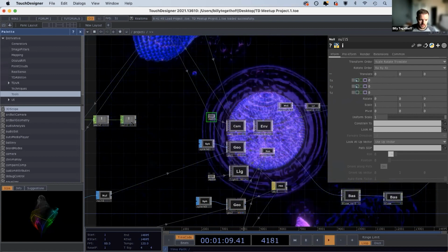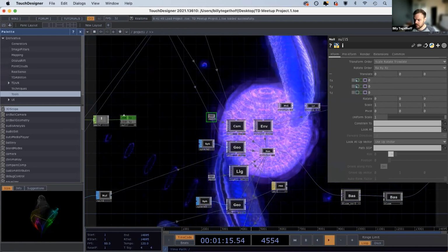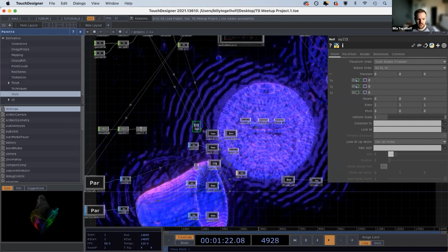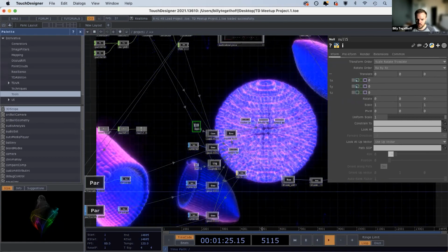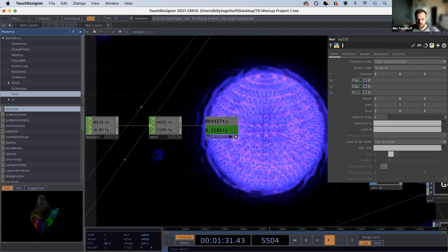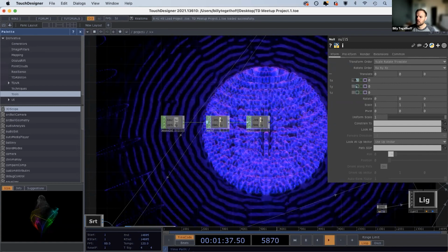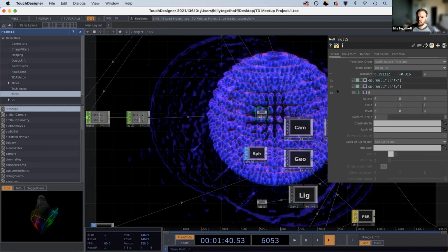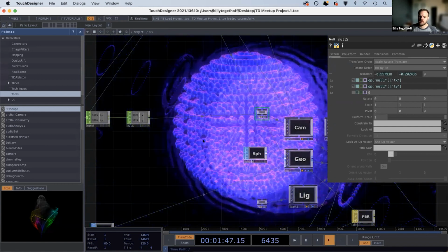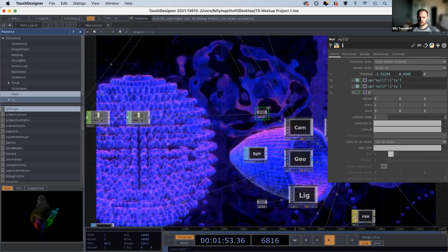Now, what you can do with that information, and where this gets interesting, is you can animate your look at point. If you don't want it to always look at the origin, the simplest version of animating it that can get a cool handheld camera look is using the mouse in chop and then animating your X and Y coordinates on there. I did that ahead of time, so you can just see what's going on here. As I move my mouse, where my camera is looking changes accordingly.